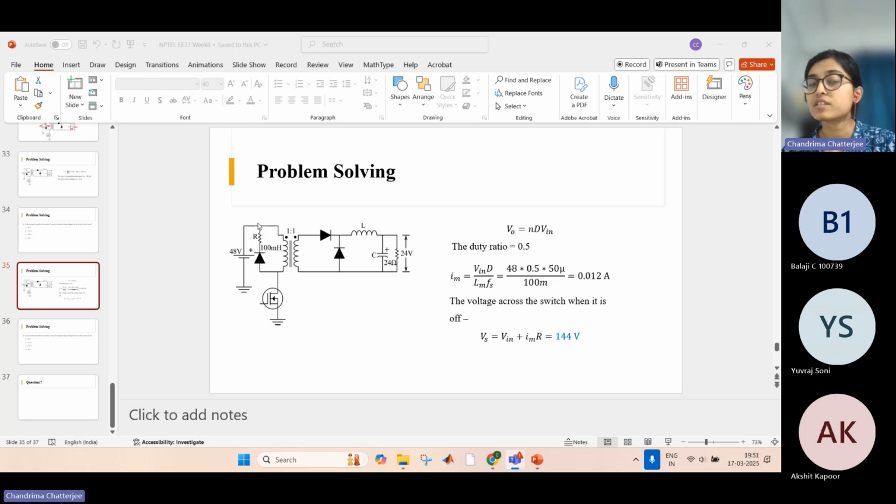But as the leakage is usually much smaller than the mutual inductance, you can take the self inductance only as your Lm, right? So for magnetizing inductance, you can take the self inductance value and calculate the Im value. Is it fine?